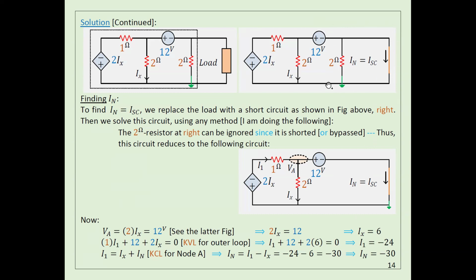Okay? That's how it is. Usually current is going to go to the easy path, or the path that has low resistance. That's what you keep in mind. I told you before, if you have two resistors in parallel, and the resistance of one of them is much higher than the other one, it's not a short circuit, but much higher. So we find most of the current will go through the low resistance. Current always likes to go through the low resistance in case of parallel. Okay, that's why I made a short circuit, so you cancel this one.